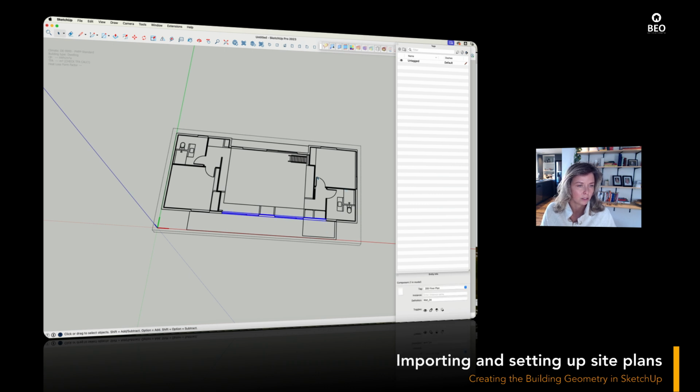That means that you can actually go into the group and work on the items inside here. And then you can highlight these areas that create a larger file and maybe simplify them, because it makes it easier for the software to calculate later on if the model isn't as complicated.